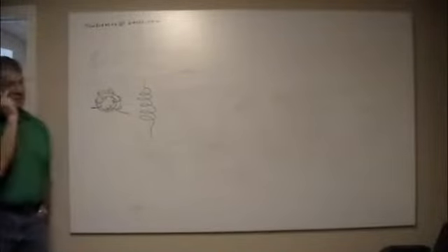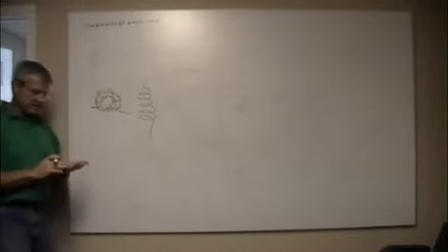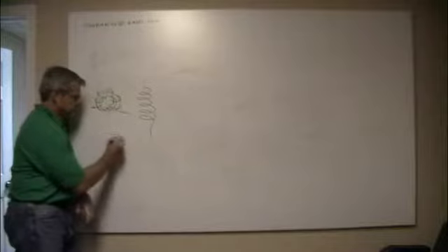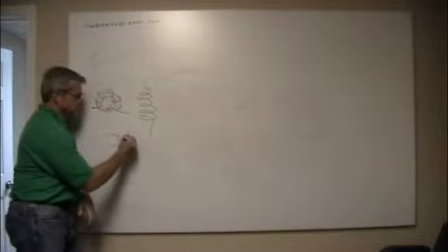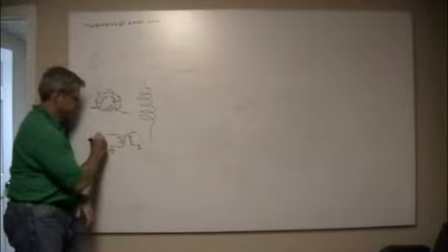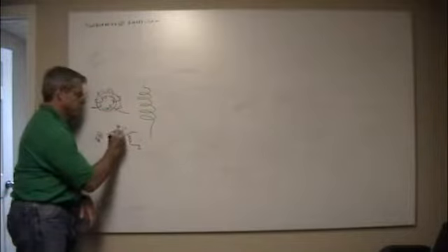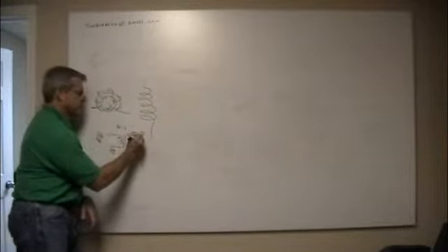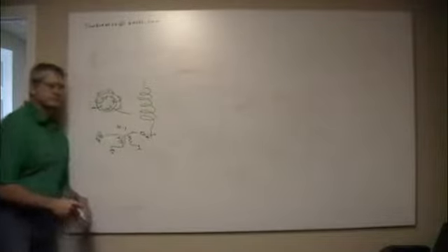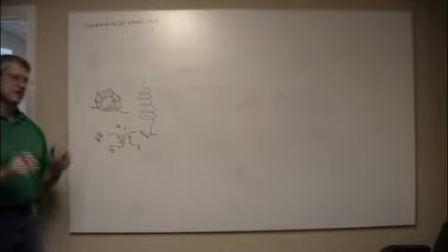Like that. So that's the iron core. You'll see these. I talked about transformers last week. Put an AC signal in, and I can get a different voltage out. So if I were to put 120 volts AC here, and this were a 10-to-1 transformer, I would get 12 volts AC out here. Simple. Nice way to knock power down, knock voltage levels down.